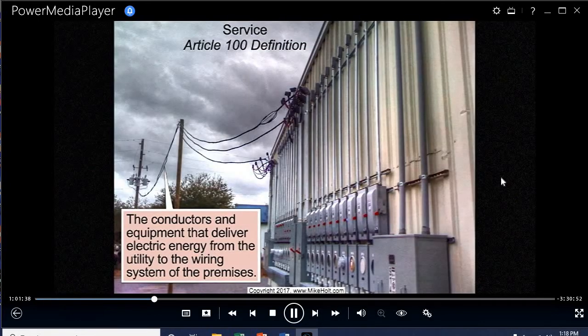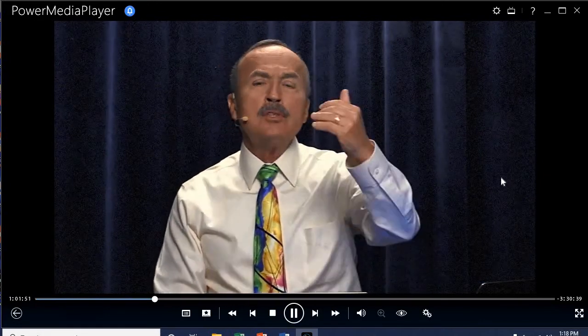Continue definitions. We're almost done here. Service. This is an important definition. People make a big mistake in not understanding what a service is. Let me tell you what I've heard in my experience. People would take a disconnecting means and run a feeder out to a remote building. And they say, well, you treat that like a service.